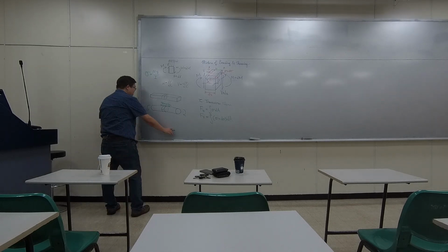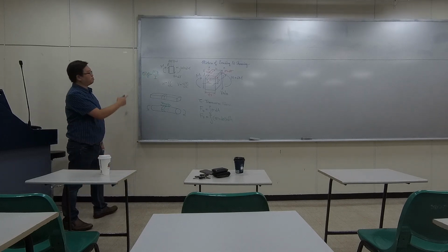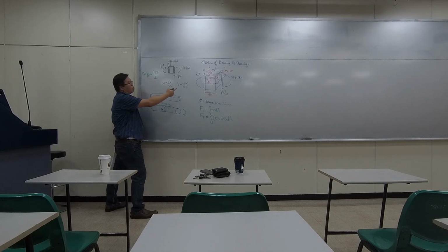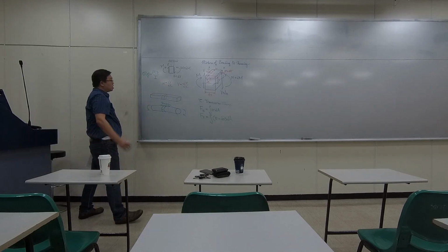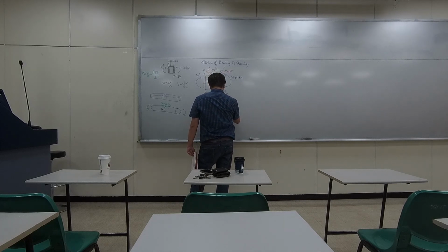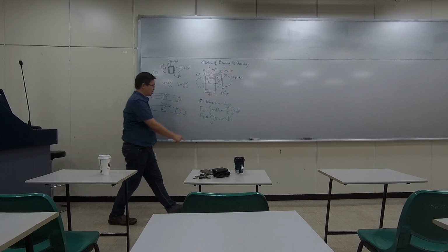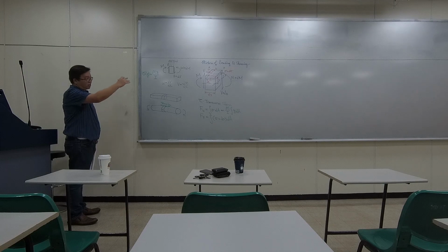So basically the stress at any position could be computed by this equation. Earlier we had Mc over I, but this time I would like to know the stress everywhere. Then it's a general equation. So we can plug it in. When we do that, M over I is a constant. The only thing left is y inside the integral, because the area depends on your position of y.